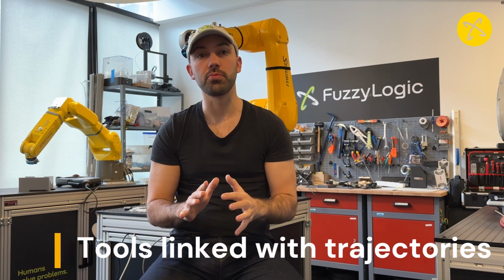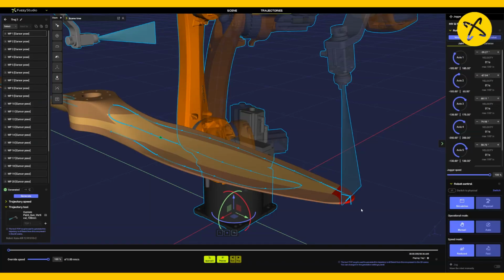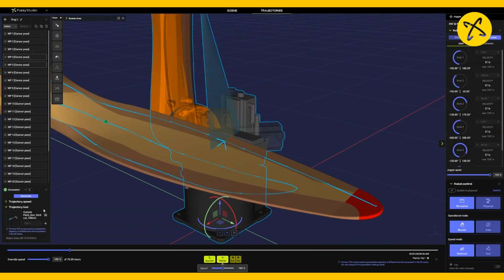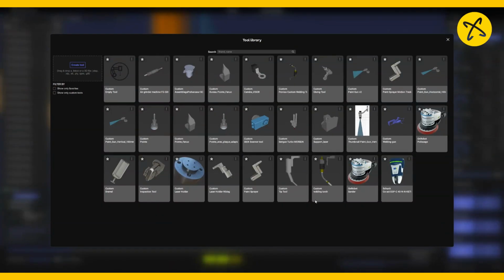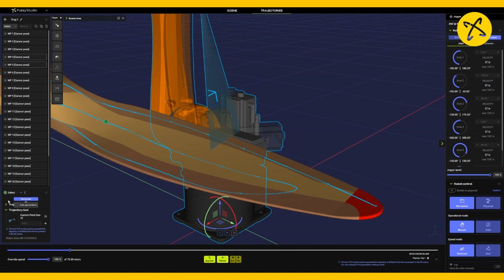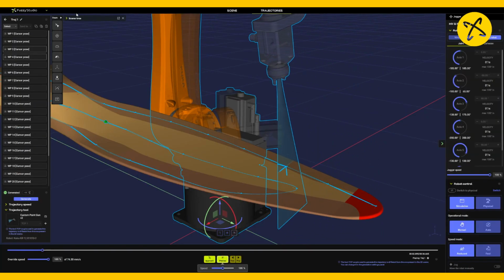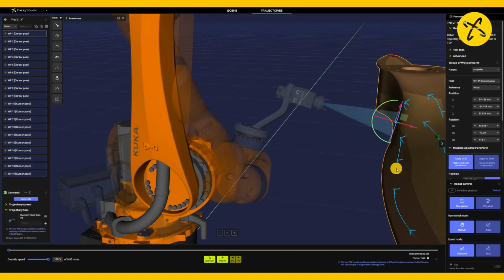This feature improves the handling of robot tools as trajectory parameters. Gone are the days of requiring the specific tool and TCP couple attached to the robot to generate trajectories. Now users can configure this directly before generating trajectories, streamlining the process and eliminating unnecessary steps. A button also lets you define the tool actually in use to generate the selected trajectory.